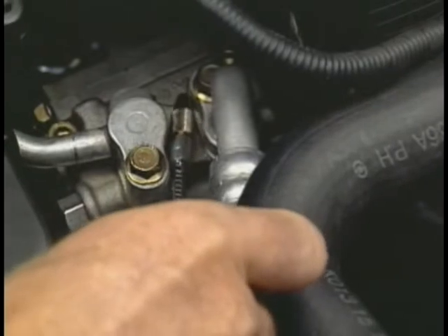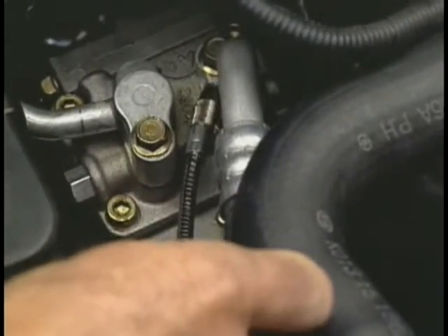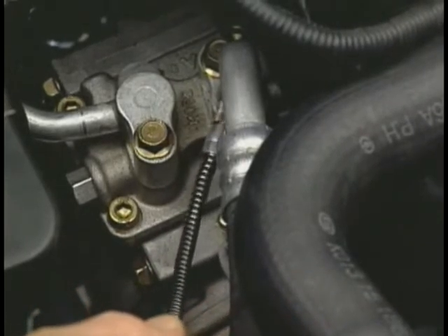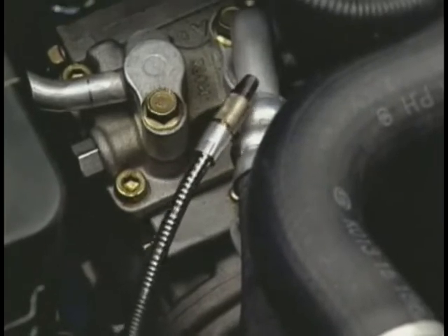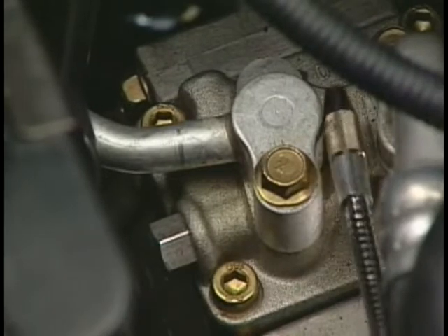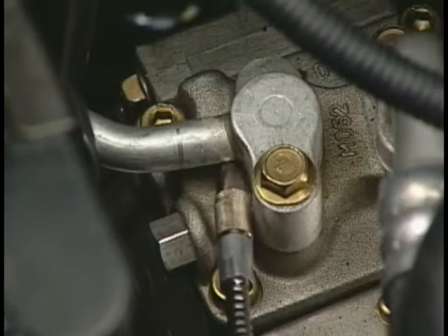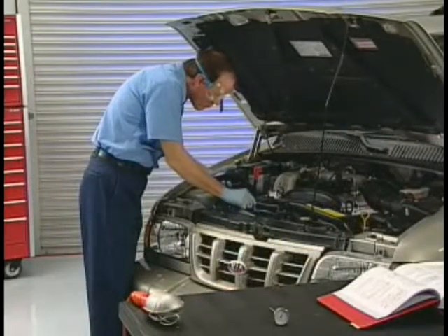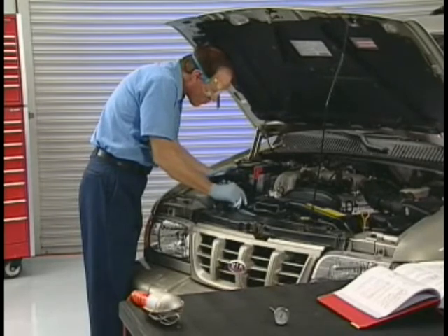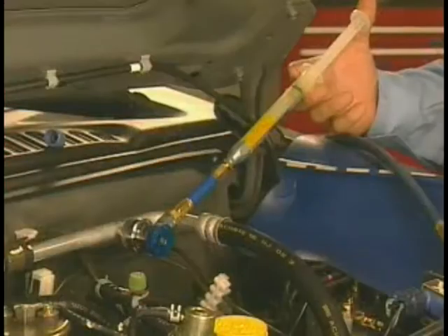To check for leaks with the electronic leak detector, set the sensitivity following the toolmaker's procedures. Then place the probe about 3/4 of an inch below the refrigerant lines, fittings, and components to be tested. Refrigerant is heavier than air, so leaks will show up under lines and components rather than above them. Move the probe slowly along the hoses and components, being careful not to touch the lines or fittings. A siren will sound when a leak is detected.